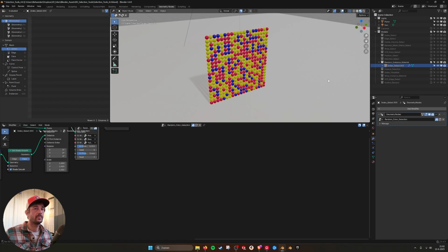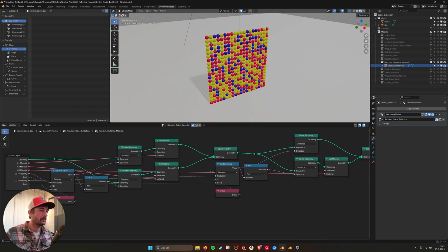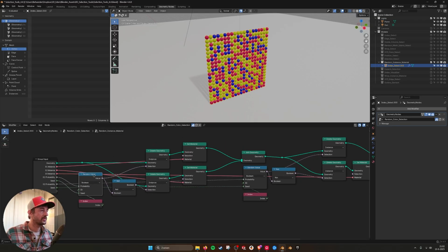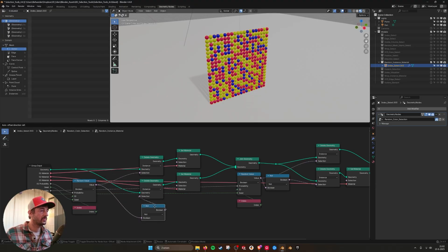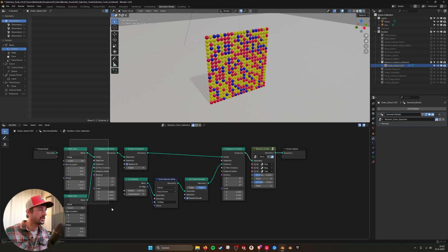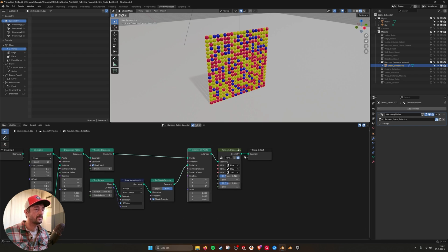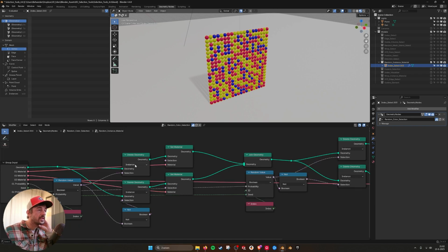Then next we have a random instances material. I found that this was also hard to do just with material nodes, but this is how I did it. So I'm using a random value with an index ID, and I flip it for the delete geometry, the second one. So the geometry comes in, which is, let me see, it's again, I'm building a grid here and realize it, instances, put the icospheres there. So it's measuring instances, here it's deleting instances randomly.